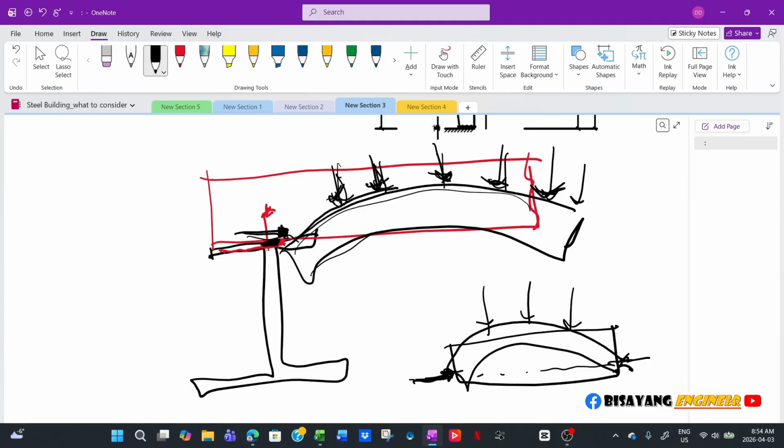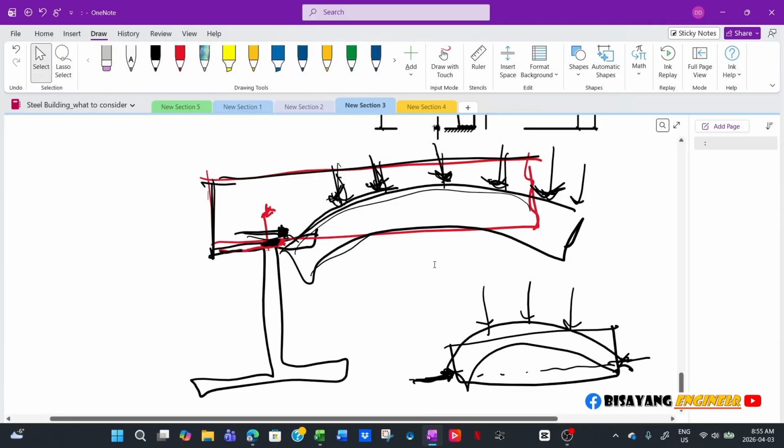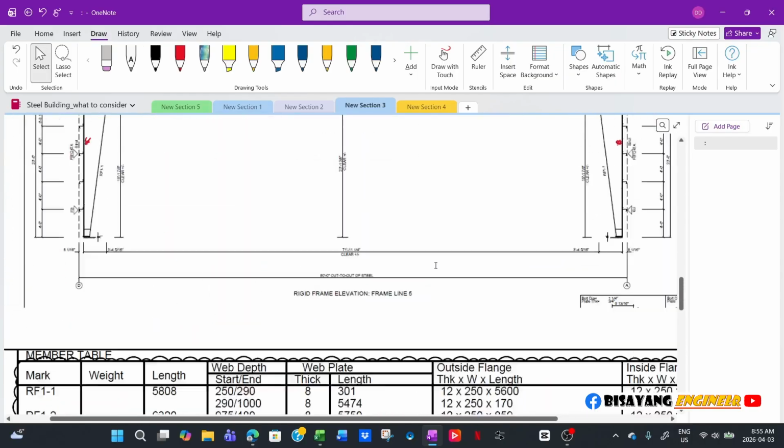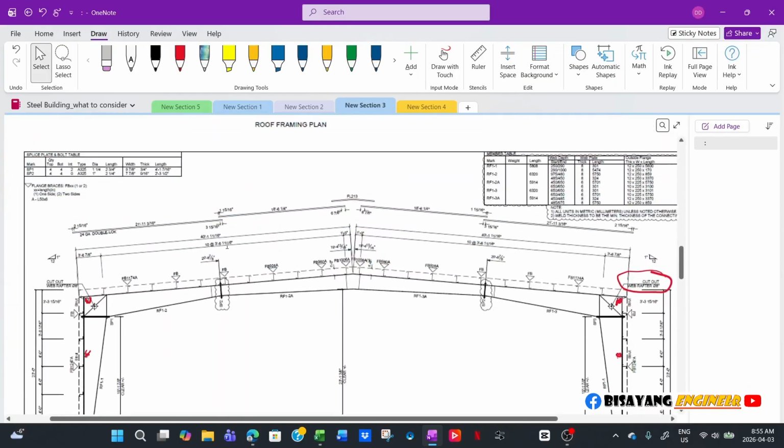That's why the purlins are used to transfer all the lateral loads to your bracing. And besides, these purlins are spaced like, what, 4 feet, 5 feet spacing. So it's more of like a uniform load, uniform support. So for example, on this one, what's the spacing here?